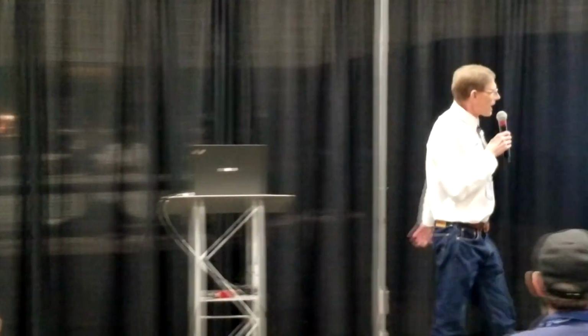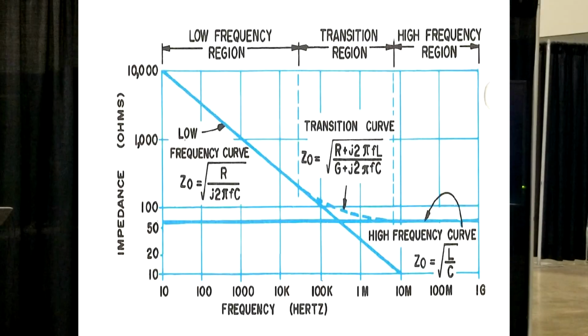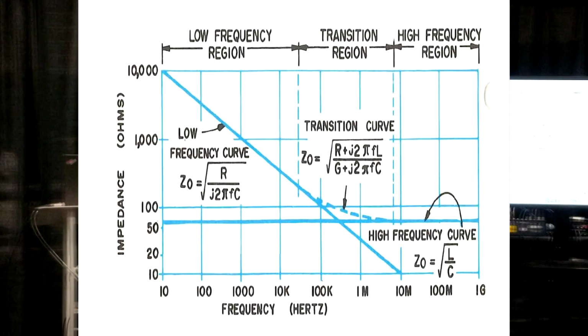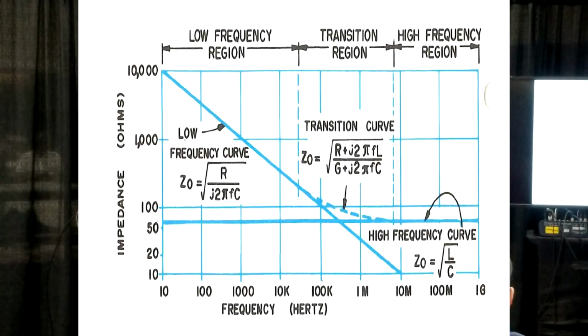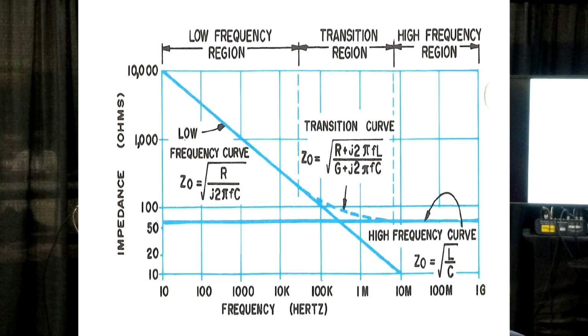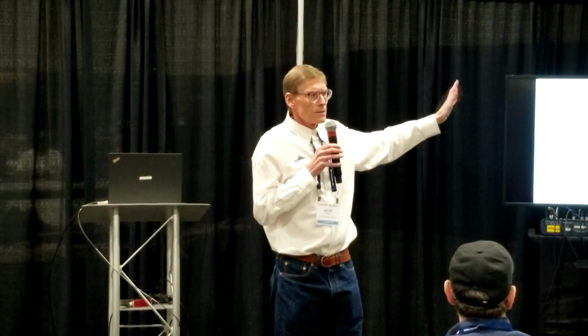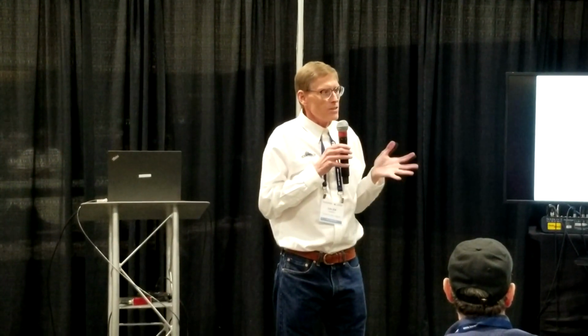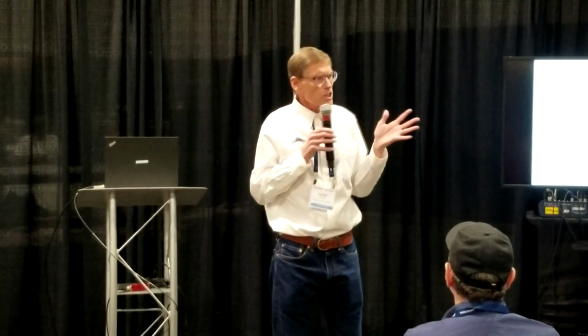We can kind of come down here to our high frequency RF equation. Everybody probably understands the high frequency RF equation. One of the ones you can use anyway is square root of L over C, inductance over capacitance, is the impedance of a high frequency RF cable. Did anybody notice there's no phase attached with the impedance of a coaxial cable at RF? They don't say it's 75 ohm cable at 25 degrees or 45 degrees or 12 degrees. It's just a number, right?